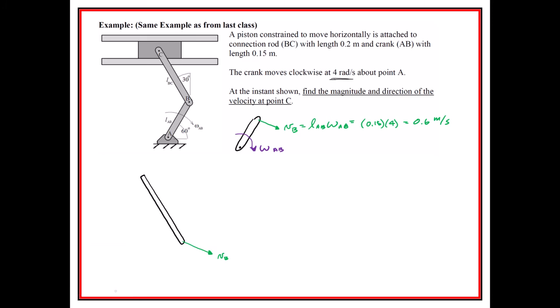Now we know that the velocity of C is going to be in this sense, right? We don't necessarily know which direction it's going to be. We will in a second. But we want to be careful that we don't use that line we just drew for the ICR. The one we want to use is one that's perpendicular to it, right?